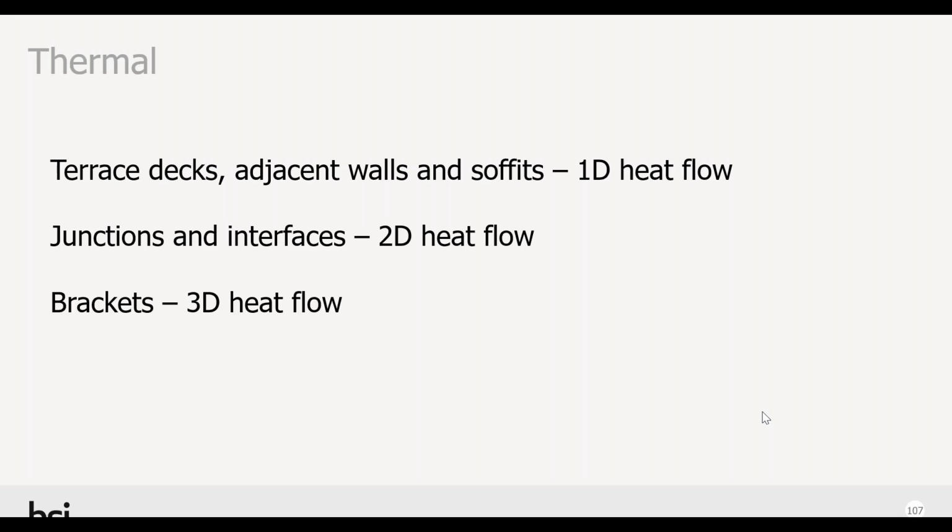And so some work needs to be done on assessing heat flow and particularly heat loss in order to comply with national regulations and in order to keep the building as energy efficient as possible, maintain comfort and prevent the formation of interstitial and surface condensation.